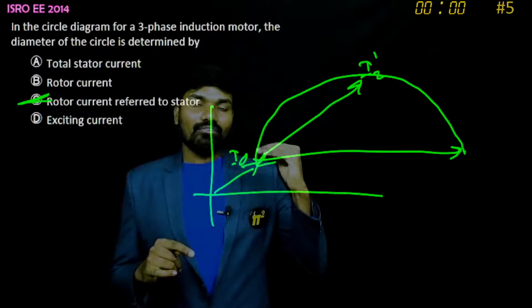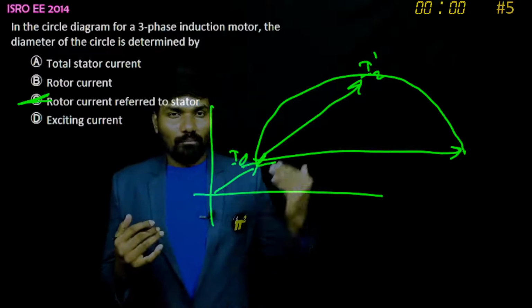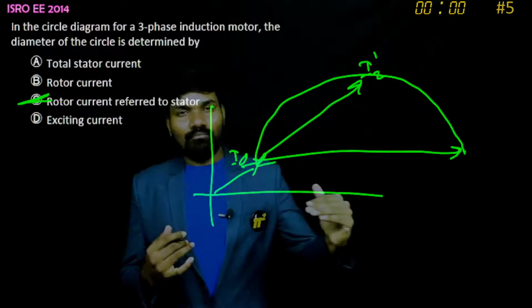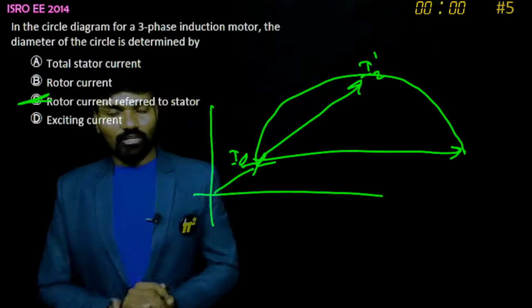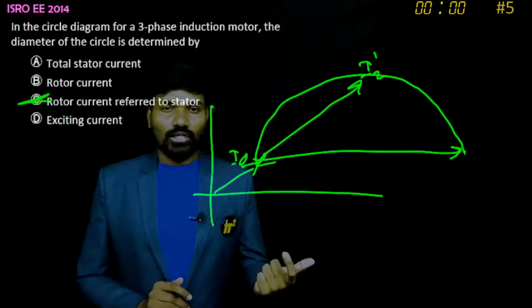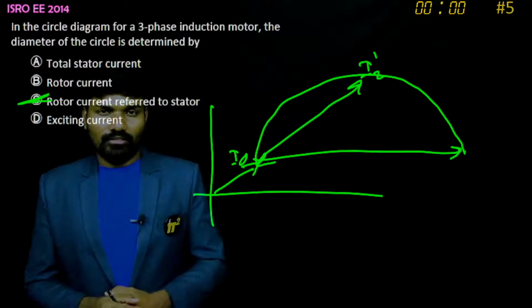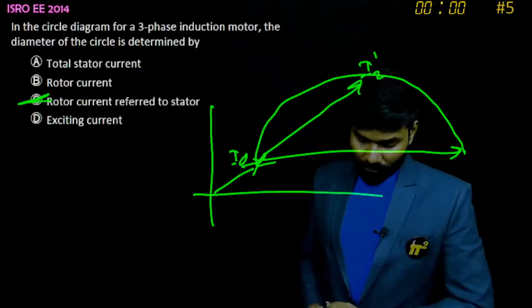If you are maintaining the same load, because it cannot obviously take the same load. But if you keep applying the same load, even though one phase is out, then obviously the motor will burn. But in the previous question, it was not mentioned anything about the load, so you cannot say that.